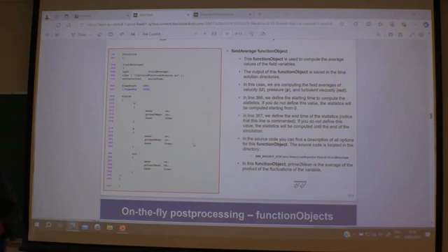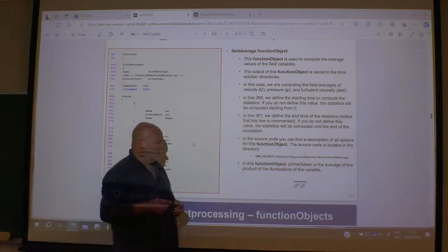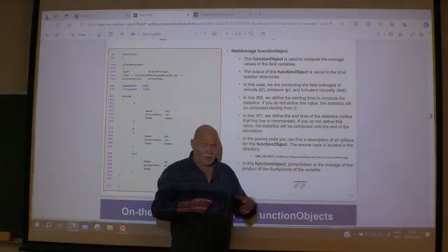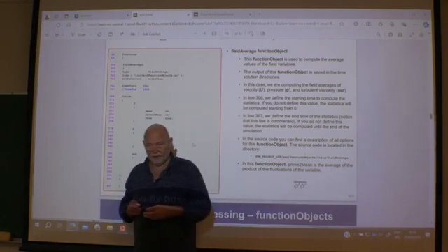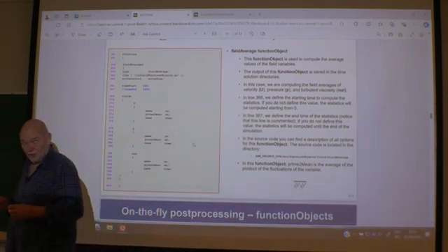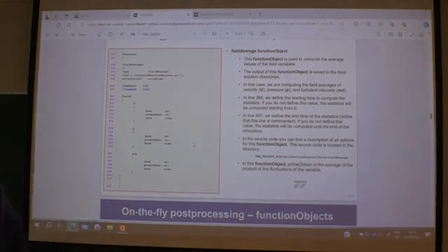Field average quantities. Well, they actually use this prime to mean function. They will actually try to calculate, say, the turbulent Reynolds stresses, if you like, or whatever. Velocity, pressure, but the fluctuating part. So yes, that's actually also an option.